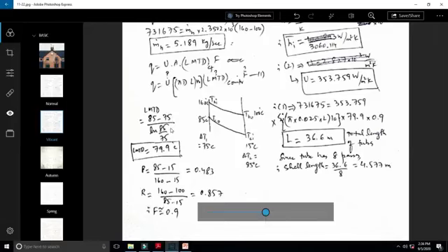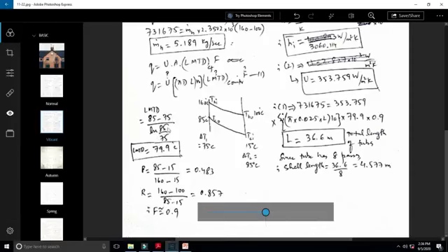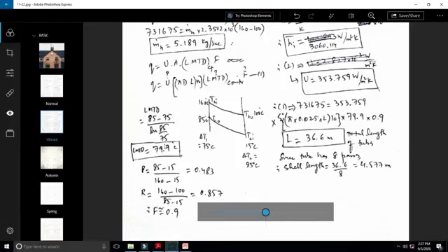The denominator will be written in the same manner the numerator has been written. If in the numerator we have written delta T1 first, then in the denominator it would be log of delta T1 over delta T2. Whereas if we have written delta T2 first in the numerator, just like we have written it over here, in the form of delta T2 minus delta T1, then it would be log of delta T2 upon delta T1. So we will get the log mean temperature difference as 79.9 degrees Celsius. It is the equivalent temperature difference over the entire length of the heat exchanger.